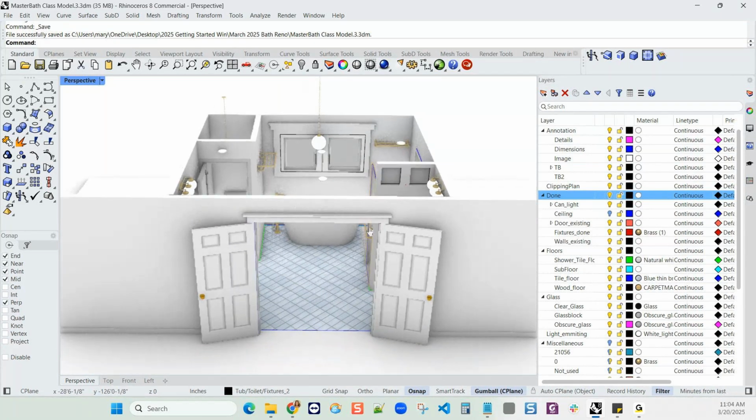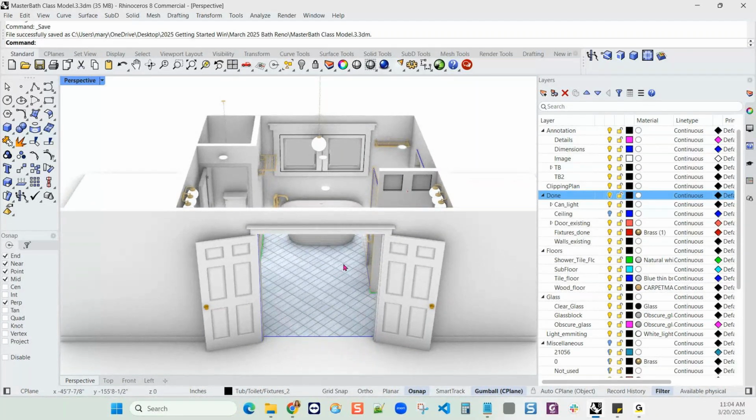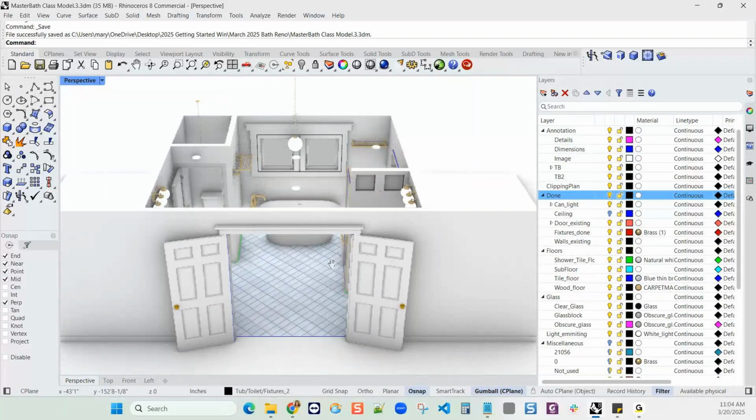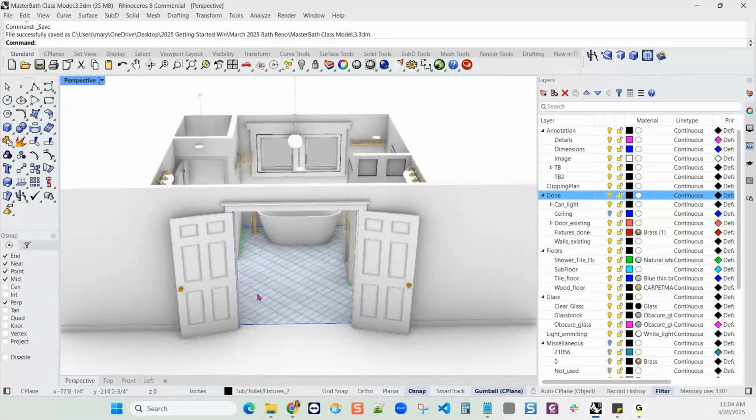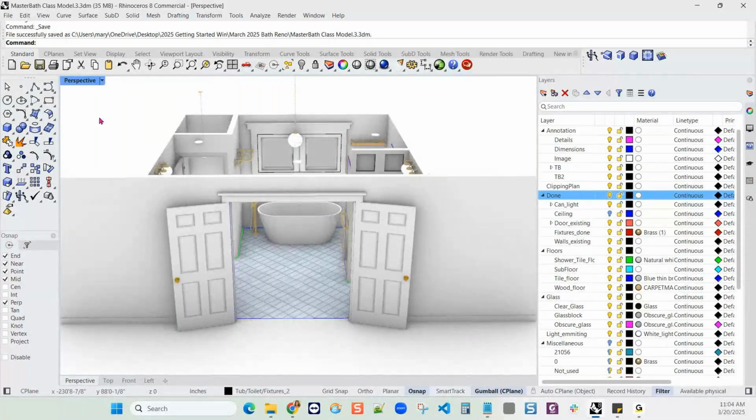And of course, there's one for the top view of the model that will show the floor plan. And the clipping planes will be set to the layout detail. That's how we create our elevations. So I want to go to the top view.